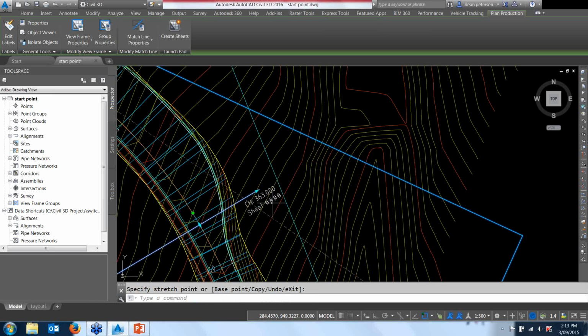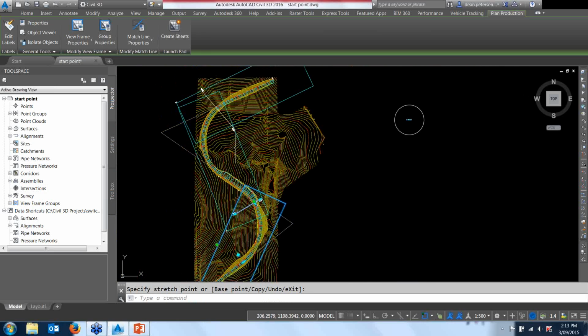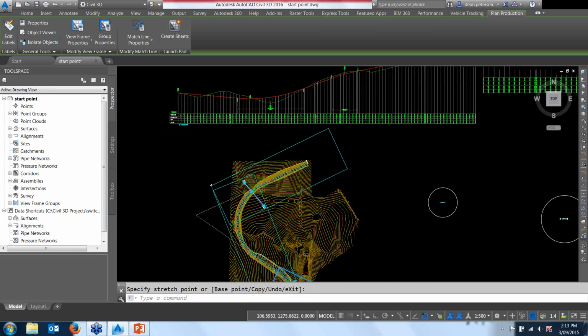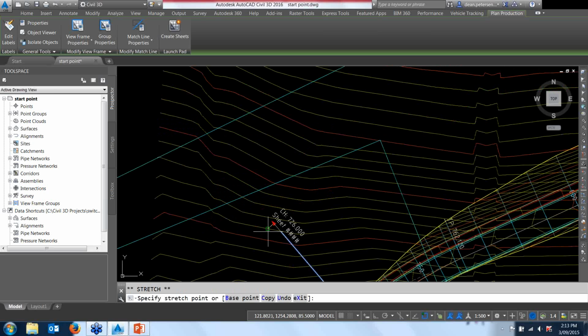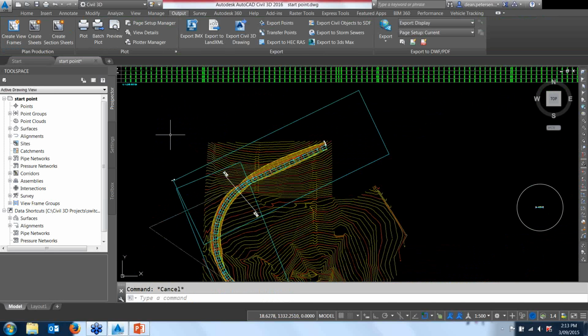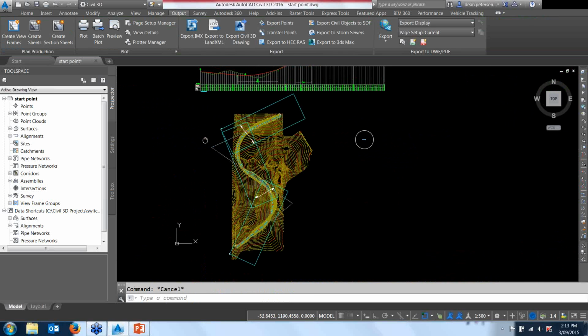Now this says sheet hash hash hash is the next sheet. That gets filled out when we actually produce these long sections on sheets using it; it actually generates its own sheet set to do that. If you don't use sheet sets, you can choose to just ignore them if you don't like them. Okay, so that's got those all lined up.